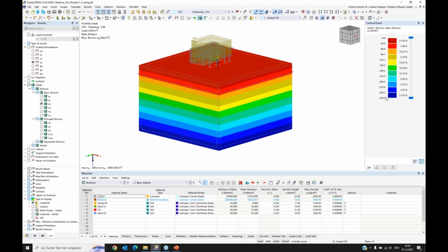And if we compare the stress we received at the bottom surface with the stress from the initial state, we can see that the stress changed only by 1%, round about 1%. So the distance of my building to the bottom surface, for example, is far enough.